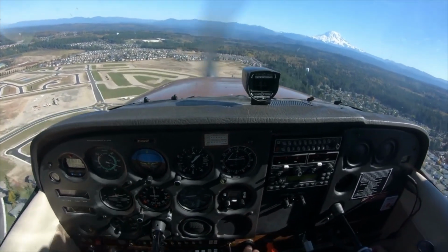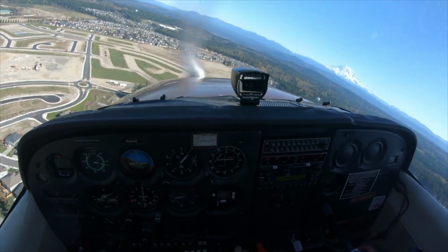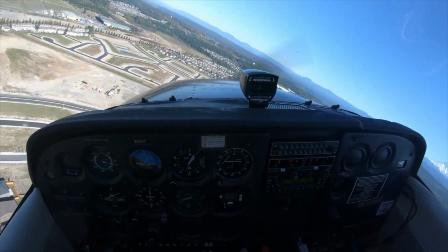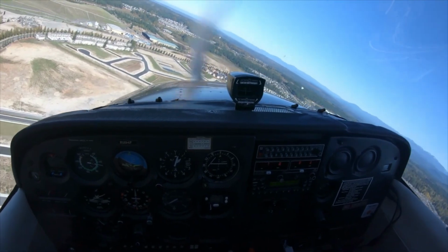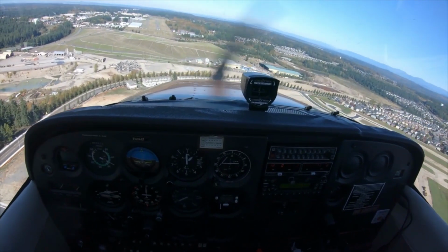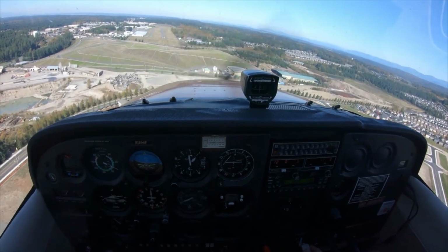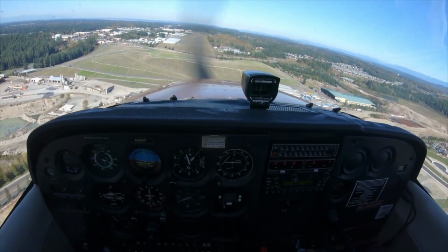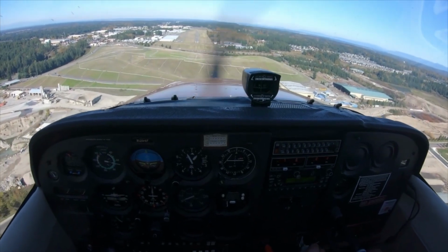For most airplanes, aerodynamic drag is the single biggest factor in slowing the aircraft in the first quarter of its speed decay. Brakes become increasingly effective as airspeed and lift decrease. The pilot increases braking effectiveness by holding the wheel or stick full back while smoothly applying brakes. Back pressure is needed because the airplane tends to lean forward with heavy braking.